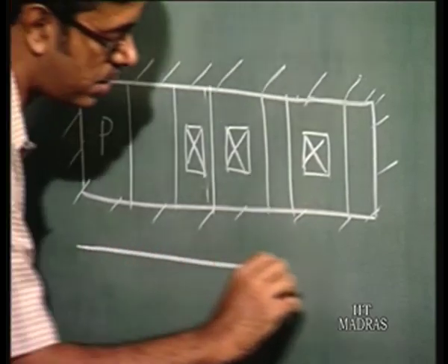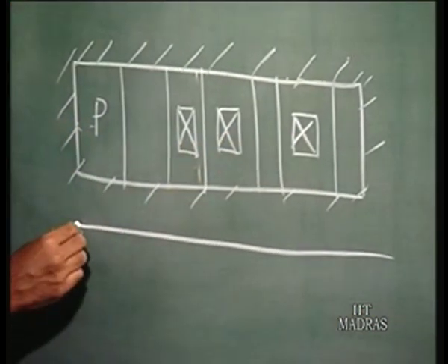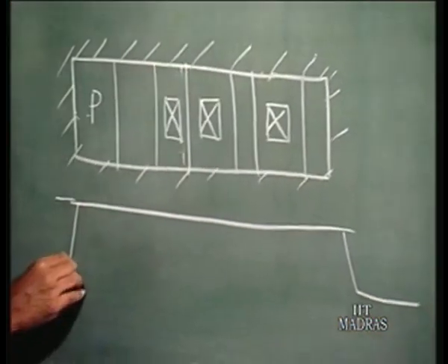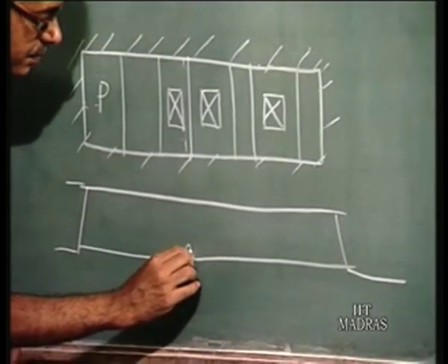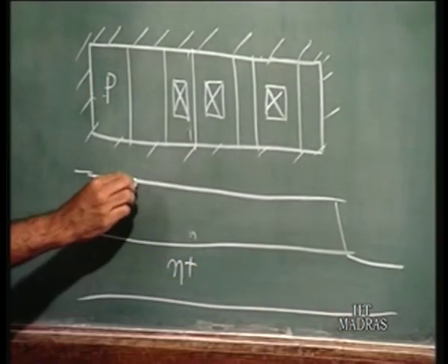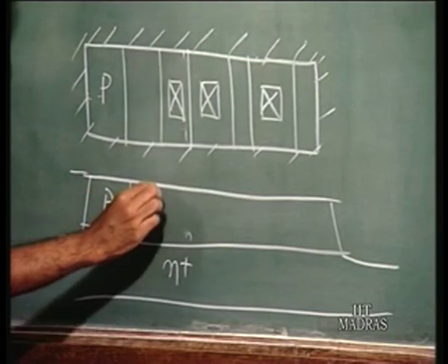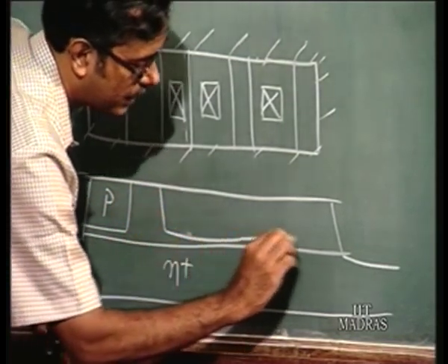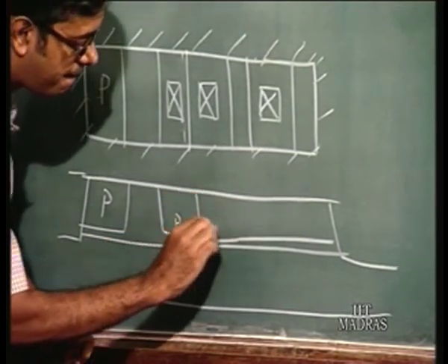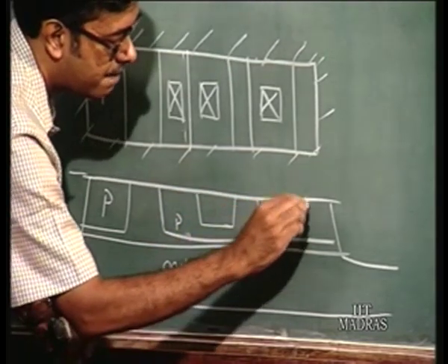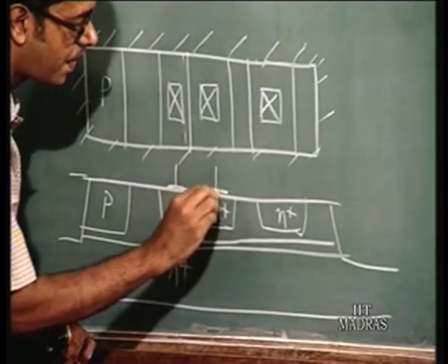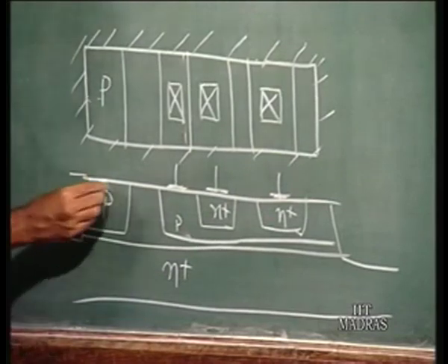So basically, if I draw the cross section across this region, you have oxide, silicon dioxide. This is N, this is N plus. All right, wafer, you have P. This goes all the way. This is the base region. This is the collector, and this is the other collector. So this is the device. I hope it is clear.